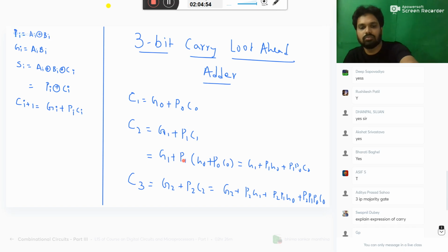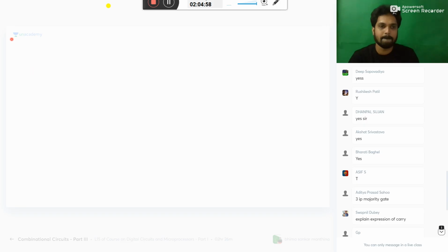So C1 is G0 plus P0 C0. What is C2? G1 plus P1 G0 plus P1 P0 C0. What is C3?